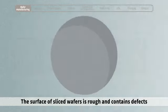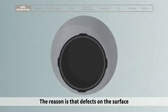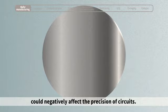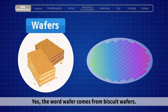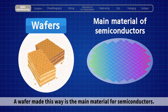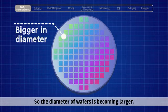The surface of sliced wafers is rough and contains defects, so polishing machines are used to polish the surface of the wafer. The reason is that defects on the surface could negatively affect the precision of circuits. If you look at a photo of wafers, you can see a grid pattern on the surface. Yes, the word wafer comes from biscuit wafers. A wafer made this way is the main material for semiconductors. Because the larger the diameter is, the greater the number of chips that can be produced per wafer is, the diameter of wafers is becoming larger.